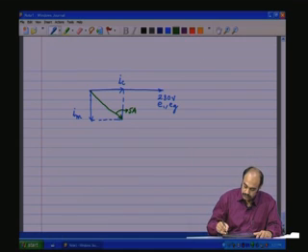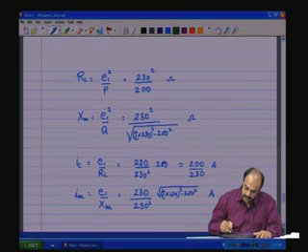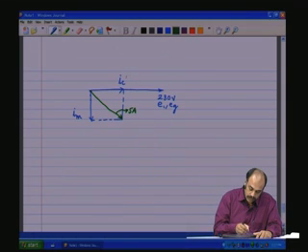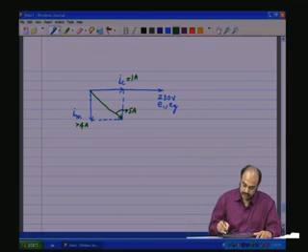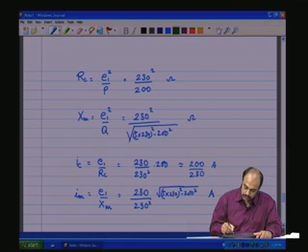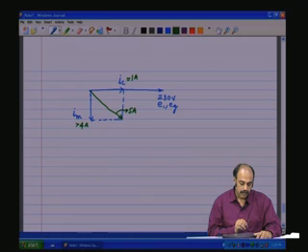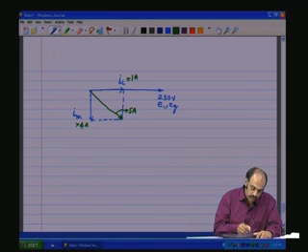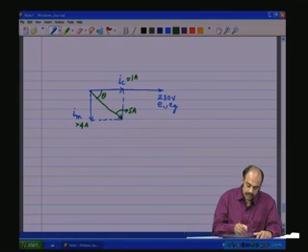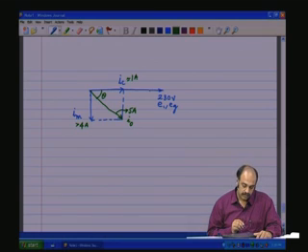So, if we look at this equation, IC is less than an amp, around 0.8 or 0.9 amps. So, this is approximately 1 amp, and IM will be slightly greater than 4 amps, so that you get the resultant 5 amps. So, this should be around 4 amps and this should be around 1 amp. So, this would be the vector diagram, and this will be the angle, this is I naught, by which the current lags the applied voltage E1 or EG.